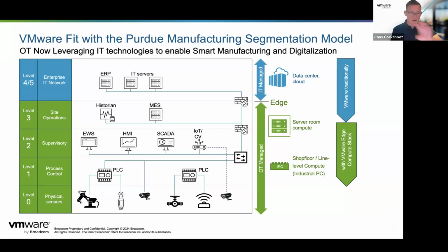So level 2 is where I've just shown you consolidation of a lot of those, like control and automation, SCADA, and the UIs and screening and computer vision. But we're now moving into process control, where we can virtualize those programmable logical controllers. Siemens, one of the leading manufacturers, released their virtual PLC last year, and we've been working with them and others on the market. And that brings some challenges. It brings the challenges of dealing with new protocols, dealing with real time, and also deciding where we stop.